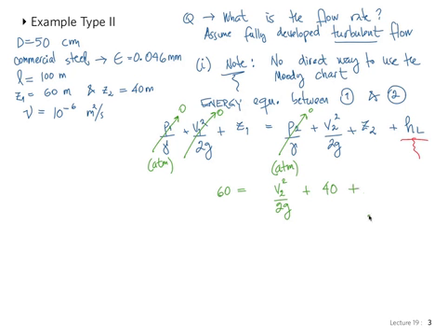For the head loss, we can use our formula for head loss, which depends on the friction factor. We don't know the friction factor. Normally we would get it from the Moody chart, but we don't know it at this point. So let's just write f L over D V2 squared over 2g. And you see here that you have two unknowns, but you can express the velocity in terms of the friction factor.